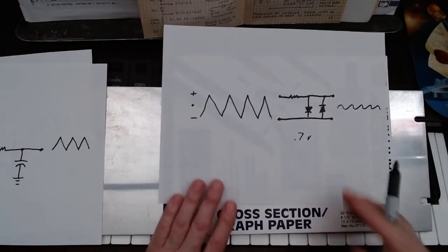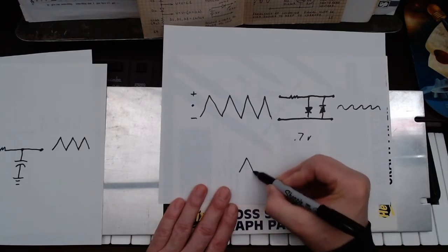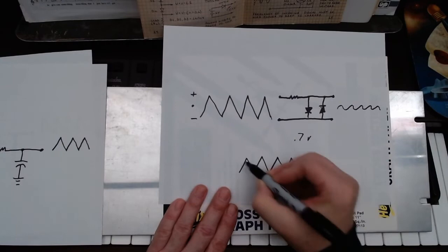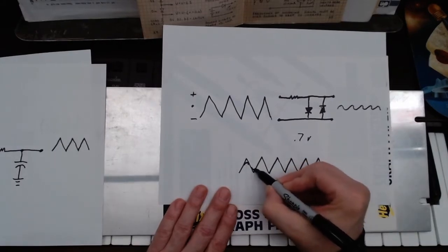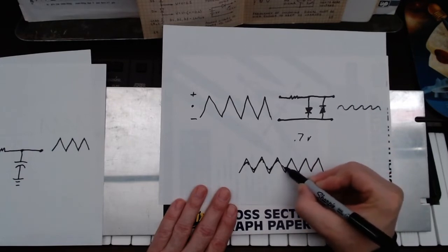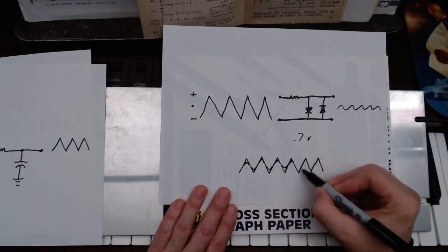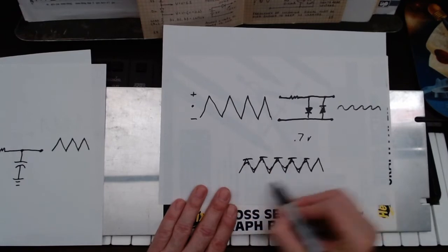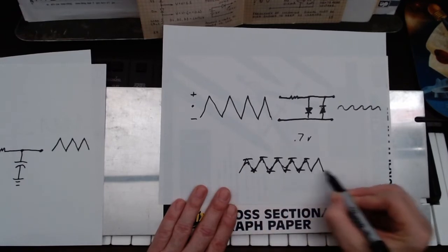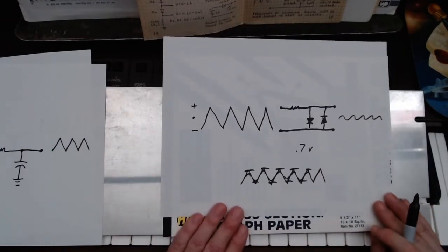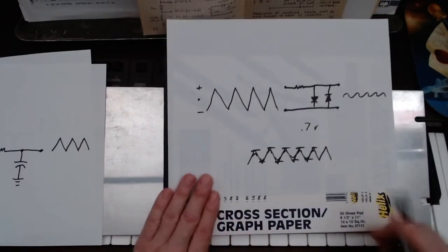And effectively, what is happening here, so we've got our triangle wave coming along, and we're clipping these peaks in a curve. And so since we've cut these points off through the effect of the barrier voltage in the diodes, now we've created an approximate sine wave.